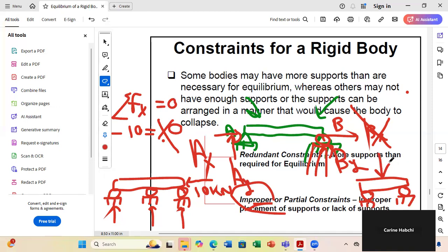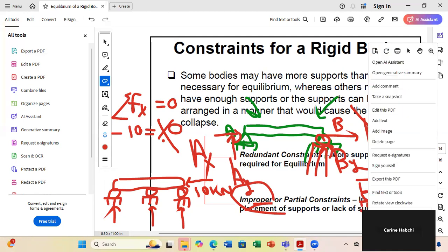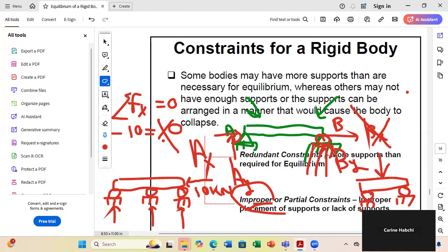If my forces acting are vertical and the net force is down, I can have equilibrium in this case because my rollers will develop upward vertical reactions in a way to cause equilibrium.